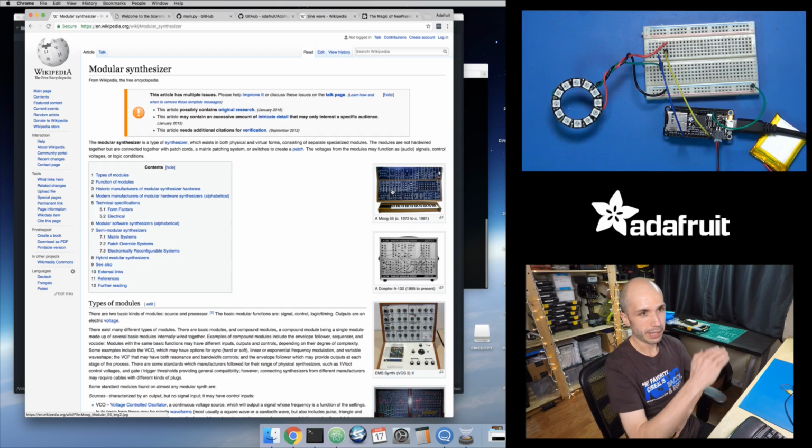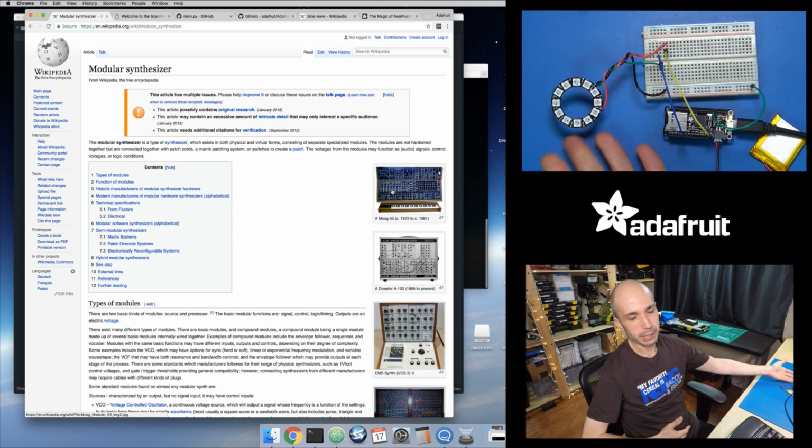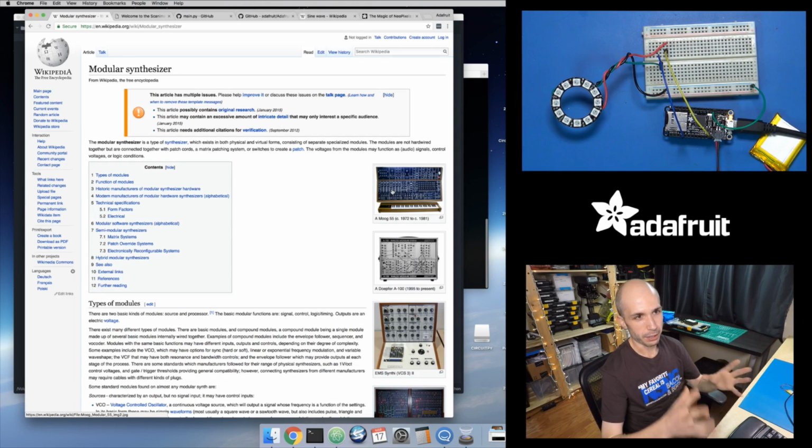It might be stuck at a value of 0 forever, so the pixels are turned off. But maybe something's driving it so that it's oscillating smoothly from 255 down to 0, back up to 255, back down to 0. It's a smooth oscillation like a sine wave. If you view that over time, it would look like a sine wave going across the screen. But if you apply that to the NeoPixel, you would see it as color pulsing.